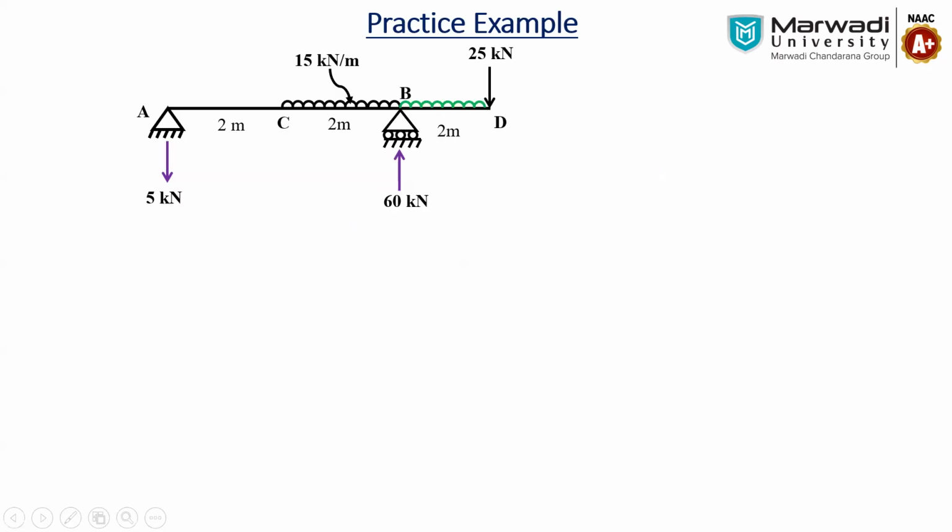Because in the actual beam there is no UDL in that span, whatever UDL is added here, that much we have to deduct in that particular span, like this. Okay. So what is the significance of it? Whenever we are taking the section X, we don't know which section X is going up to. So always keep this rule in mind, that the UDL must always be completed up to the right hand side portion.